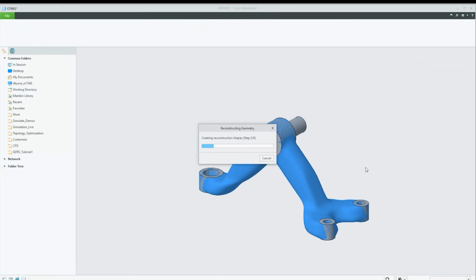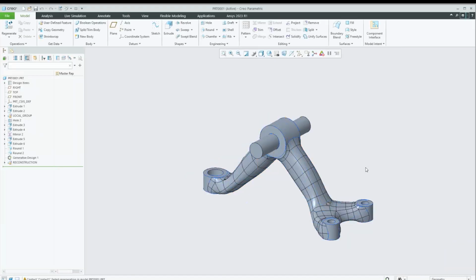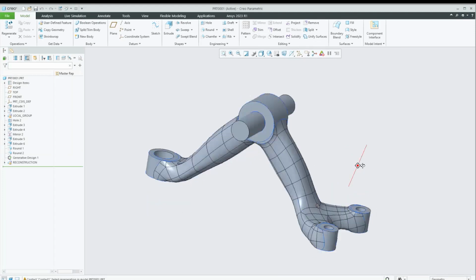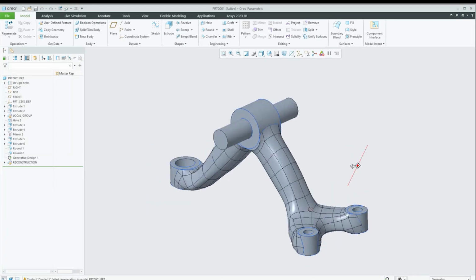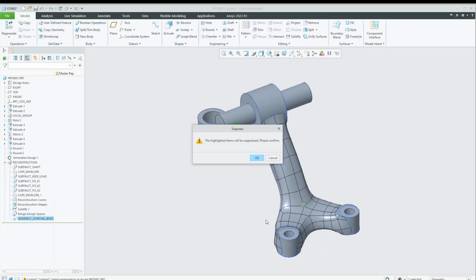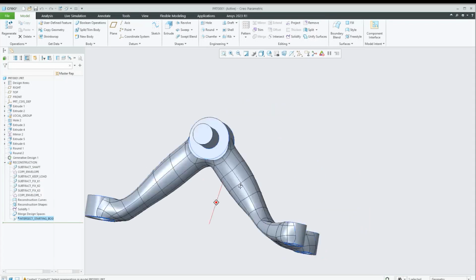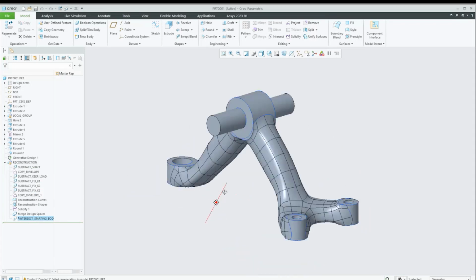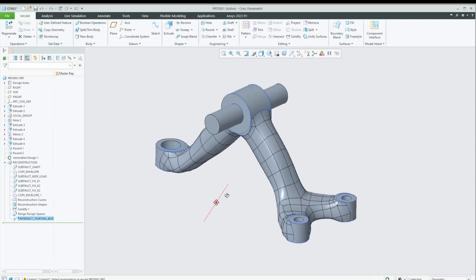And it's basically creating a freeform surface, wrapping it around the optimized geometry, but also intersecting it with the original keep regions. Those are the cylindrical regions around the part. I'm actually just going to make a small suppression here because there's a feature I don't want. But we can see here we have a beautiful CAD solid.